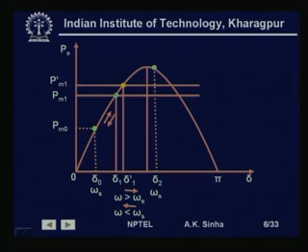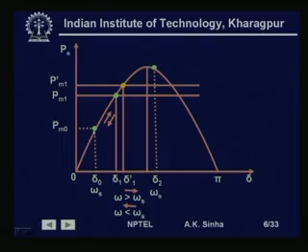At this point we will start gaining more and more speed, and the speed will keep on increasing, and maybe somewhere around this point the speed will again reach the synchronous speed, and at this point when it reaches the synchronous speed, what is the position? The electrical output is much less than the mechanical input. So, it will again start accelerating. So, acceleration will take place.